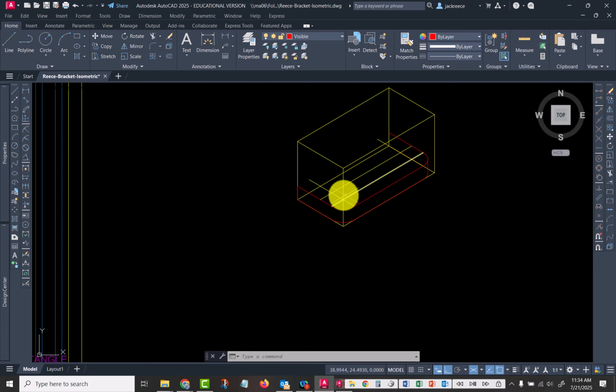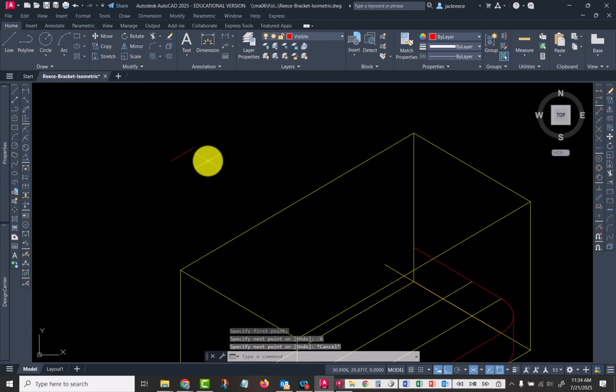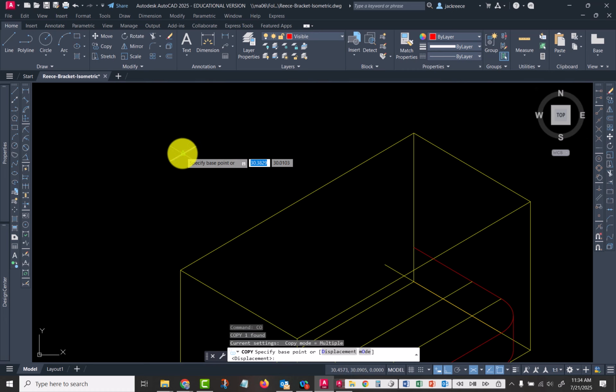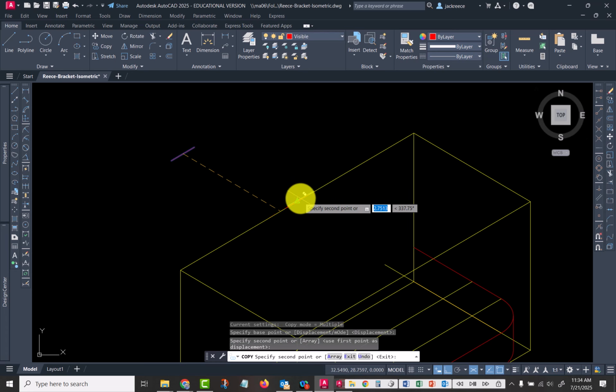Instead of working on the slots, I want to work on this back part back here. And so instead of trying to figure out how to draw that into the place, I'm just going to draw me a line that is 0.6 long. Okay, and because this thing is symmetrical left to right, I can copy this using the midpoint and copy it to the midpoint of this line.